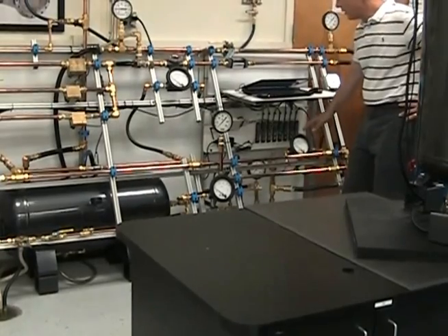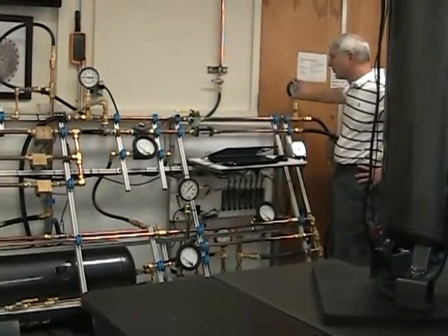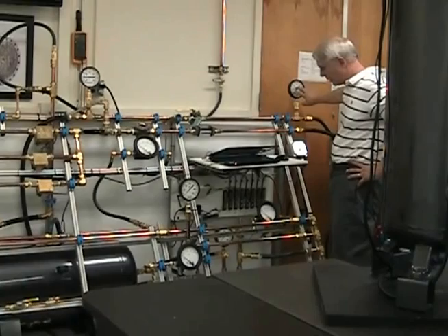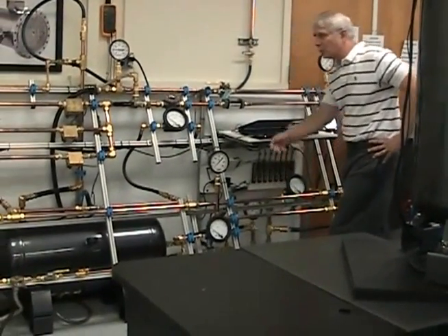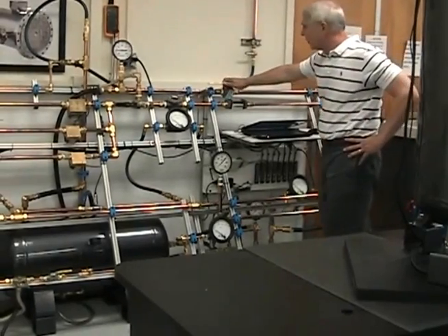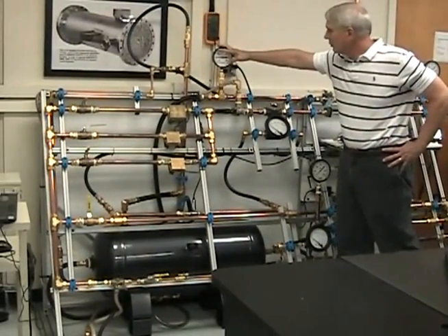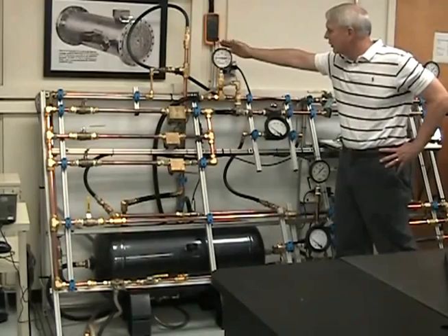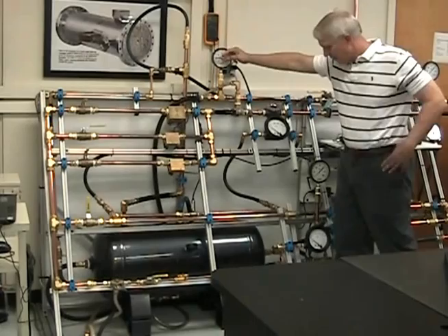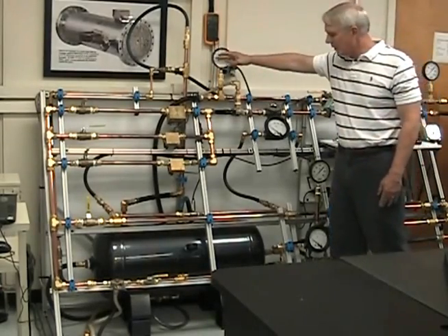And then as we go downstream, I have a few other pressure gauges. I have one right here, which is just prior to the control valve, and you'll see that this pressure is probably going to be a lot less than what's coming out of the pump because we have a lot of losses in the pipe system. After it crosses the control valve, there's another gauge up here, and you'll notice this one shows gauge pressure, but it'll show a negative pressure. I put that there because it turns out that the pump is actually creating a suction downstream of this sometimes, and the pressure in here is going to be very low.